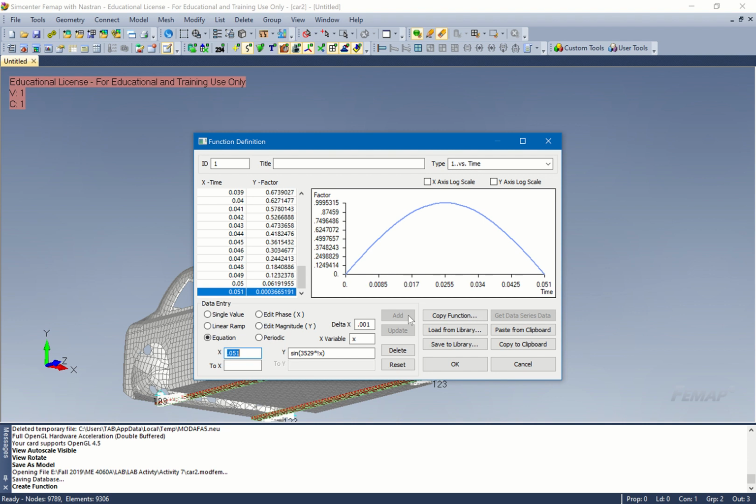So we're gonna say single value now. Here, go enter single value, and we're gonna say 0.1, doesn't really matter, 0.1 here, and then equal 0 for y. Just put 0. That make sense? So we're gonna add another data point that says at 0.1 seconds, the value is equal to 0. Say add, and you can see what it just did, right? It just added this on. So now if it extrapolates anywhere in this region, it's gonna get 0 input.